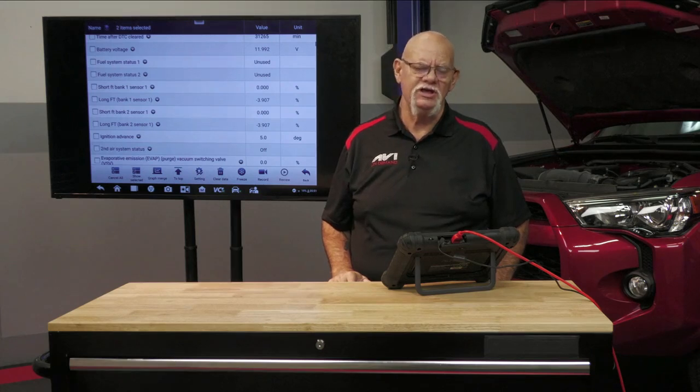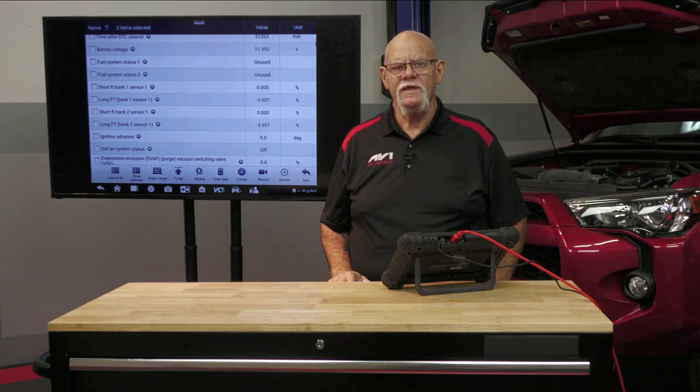It could be a lazy oxygen sensor, air-fuel ratio sensor. It could be a misfire that's putting oxygen into the manifold exhaust. It could be a cracked manifold, a blown manifold gasket. We just know we can't always call it misfire. It's not a fuel sensor. It's an oxygen sensor. So it's all based upon the amount of oxygen in the exhaust. But ideally, the concept is that the computer is adding fuel to try and fix a lean condition, or it needs a slight amount of fuel to get closer to perfect.